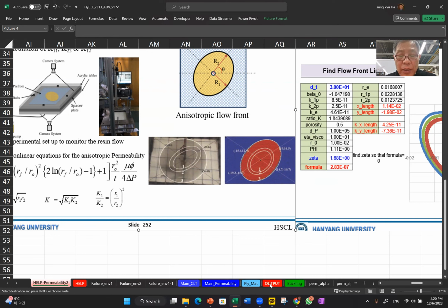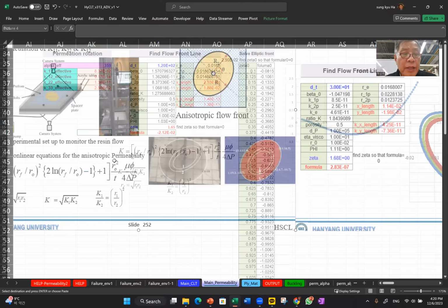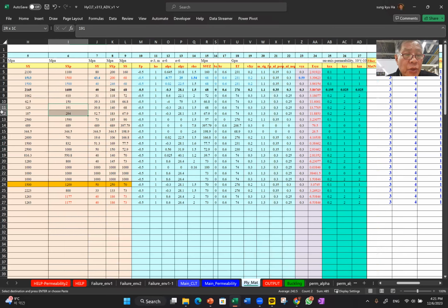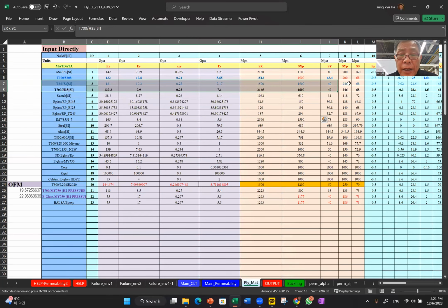K12. So here, starting again, similar to stress analysis, you start with selecting a material number, a layup sequence, and a thickness. Let's get back to the regular 0.125 thickness. And then we chose number 4. What does it mean? Number 4 means that we chose the T700.